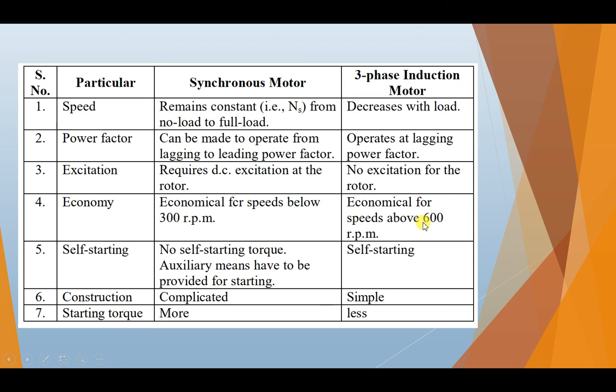The synchronous motor is not self-starting, that is we require some arrangement for this, and the induction motor is self-starting. The construction of the synchronous motor is complicated as compared to the induction motor, and the starting torque of the synchronous motor is more as compared to the induction motor, which has less starting torque.